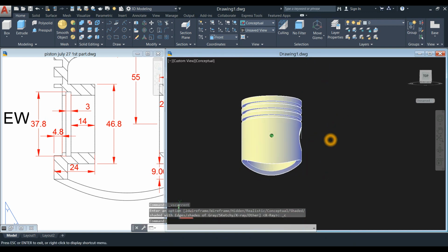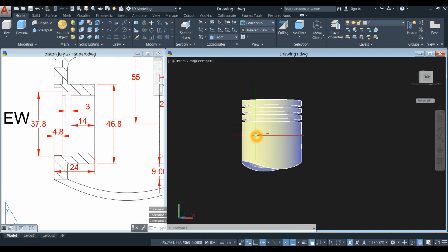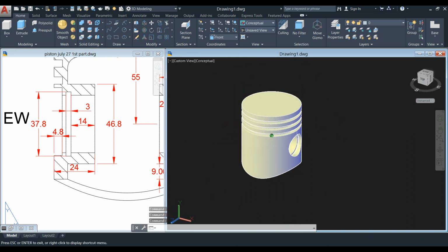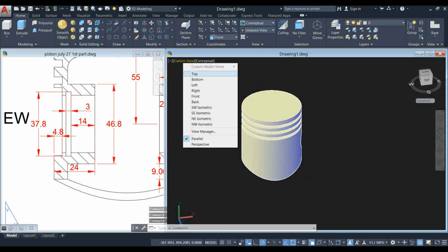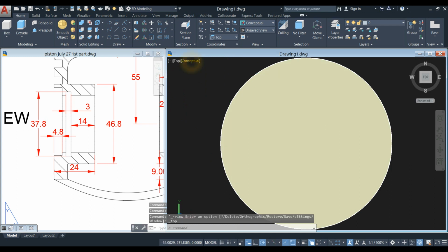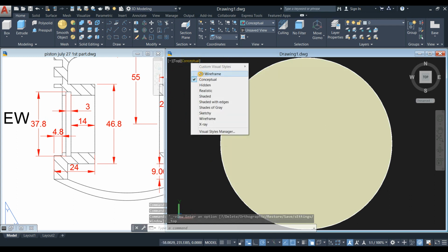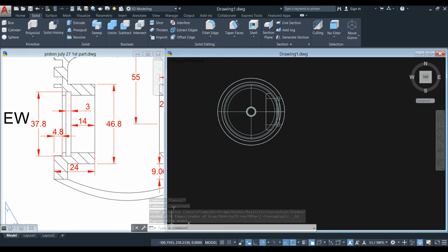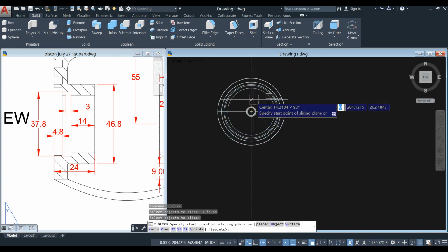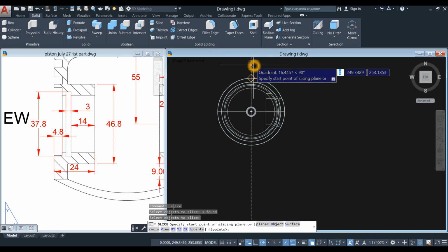Alright, so I'm gonna poke a hole here on the other side, but I don't want to go through all that hassle, so I'm just gonna bring this to top view, change this to the wireframe, and go to solid, select slice command, click this object, right click, and just hover from the center, and then don't click, and move your cursor along the y-axis.